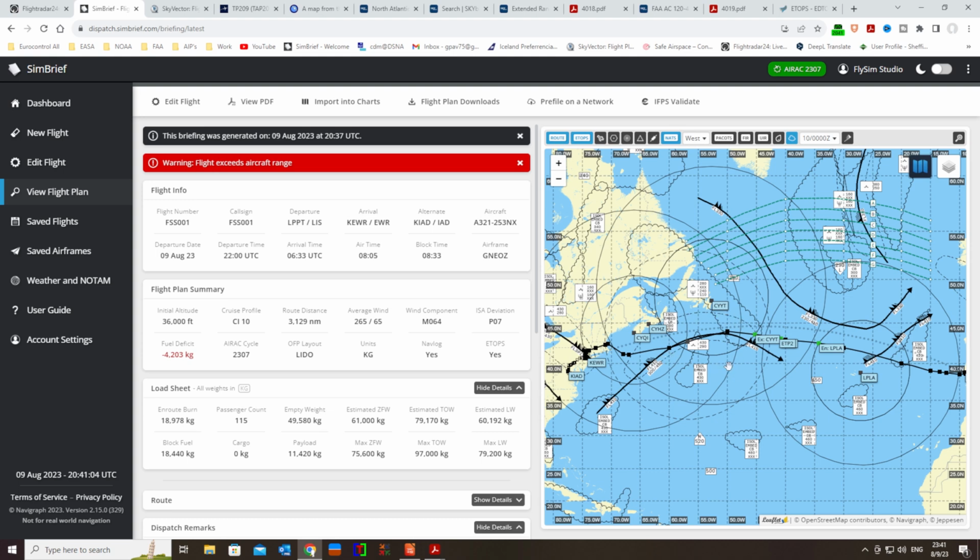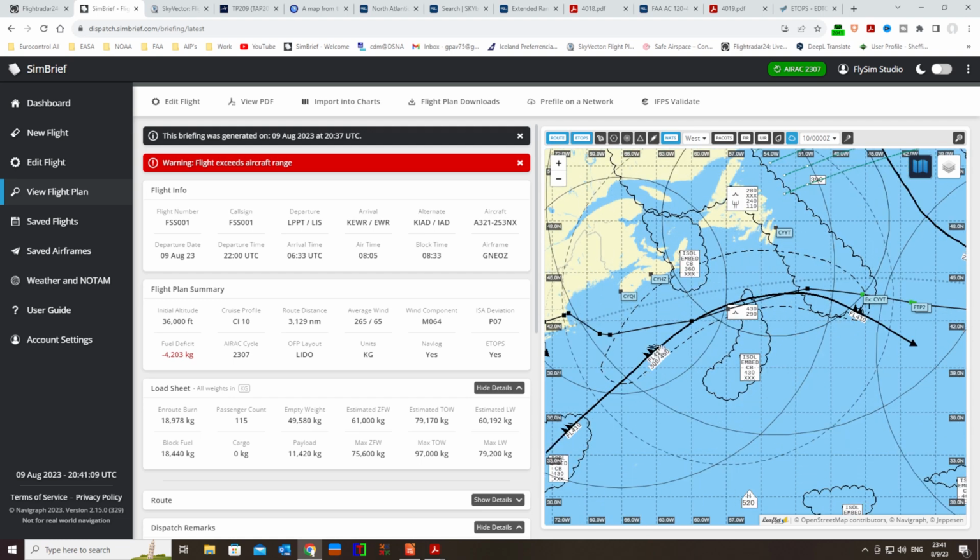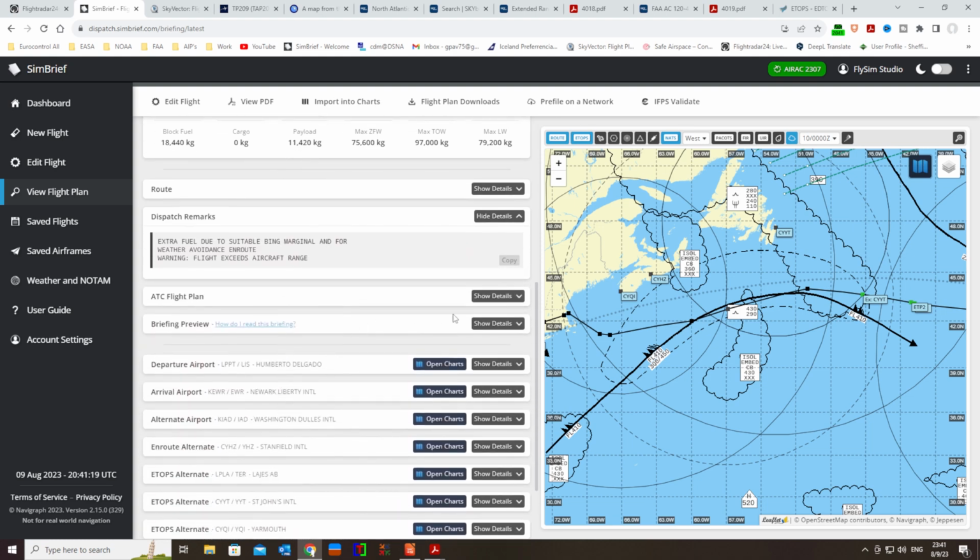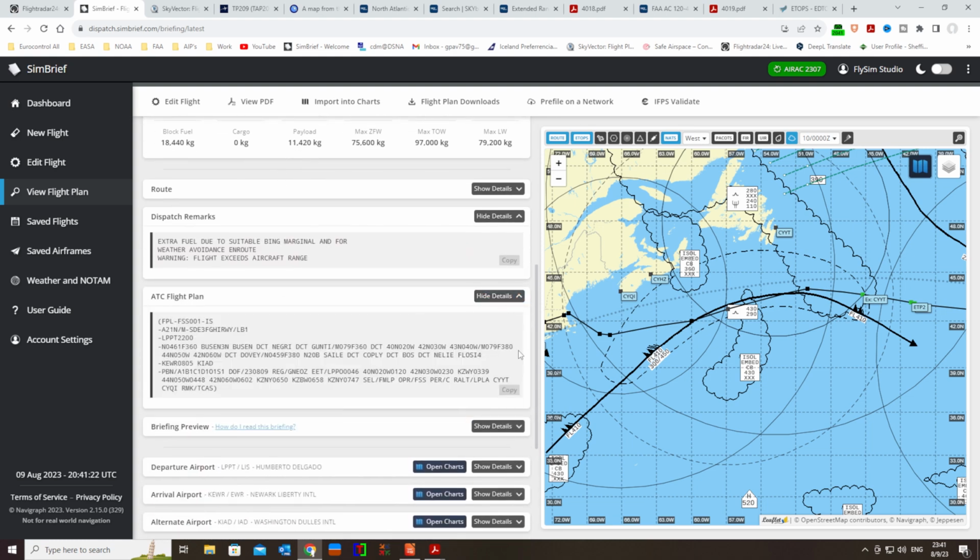This, and I'm close to 360, and the jet stream, if you see here, is from 300 to 45. With the core being at flight level 410. We're not that high, but we are getting there. 360, 380. Okay, maybe I have to reduce my flight level, sticking in 360 all the way in. Maybe that will save some fuel. You don't have to go always higher. You need to take these things under consideration also.